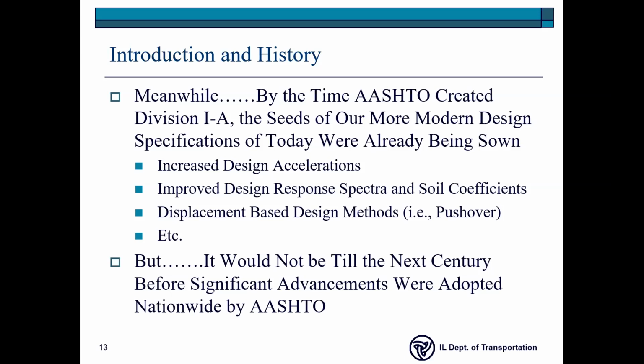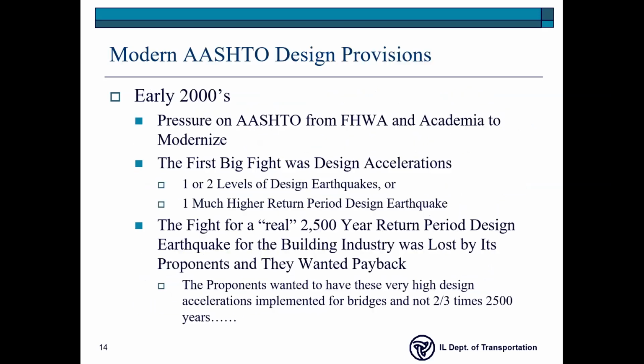So there's force-based versus displacement-based. And the easiest way to describe the two without getting into any detail at all is that displacement-based is a very theoretically accurate way to do seismic design, and R-factor is sort of like an approximation of displacement-based. Okay. But of course, it would not be until around the early 2000s before anything new got adopted.